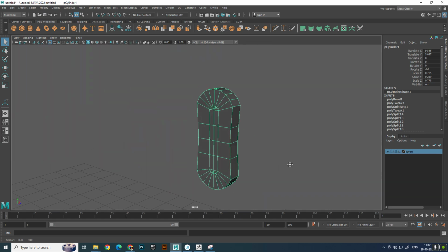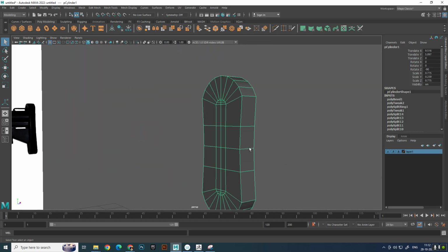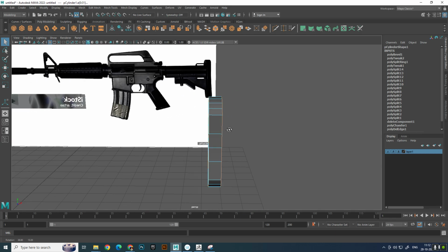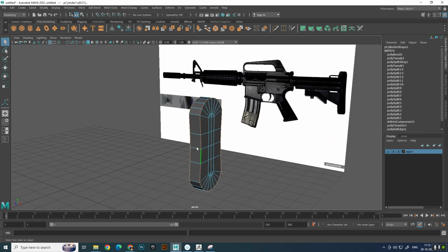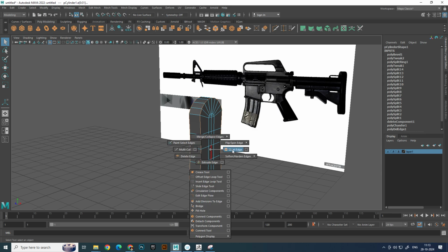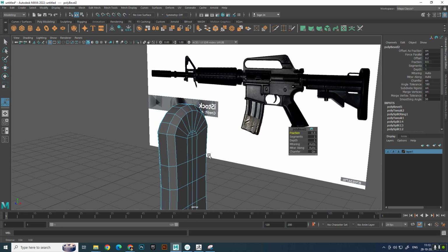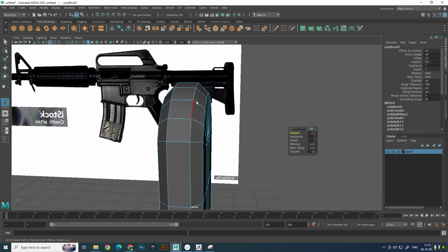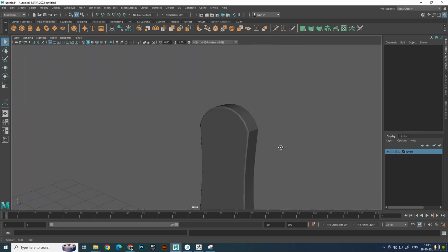When you get the shapes like this, select this edge and this edge, both the opposite edges, and bevel it. The size of the bevel is big if you compare here. So what I will do is 0.02, 0.01, make it smaller, not more than that, enough.